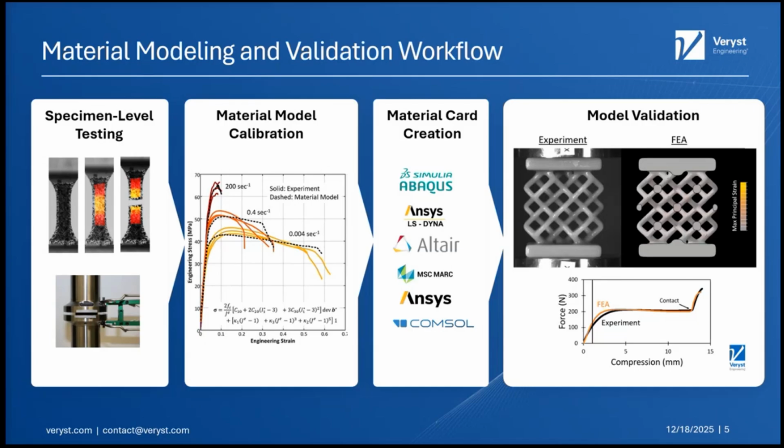How do we decide loading, unloading strain for cyclic loading test and calibration process? Slide number 19. Is it a problem if the curves intersect in the graph for calibration purposes? I'm not sure I understand that second one, so if you could add a little bit more there. But how do we decide? That's a combination of what I think is interesting in the material and what's interesting in the loading scenario. So if I expect my loads to put about 5% strain on it, I'm going to want one or two of my cyclic loading points around 5% strain, 4%, 7%, something like that.